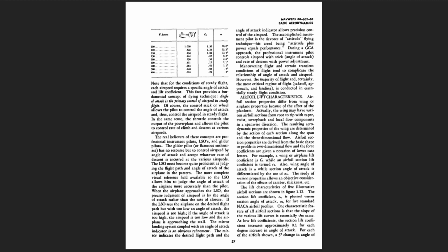The mirror landing system coupled with an angle of attack indicator is an obvious refinement. The mirror indicates the desired flight path, and the angle of attack indicator allows precision control of the airspeed. The accomplished instrument pilot is the devotee of attitude flying technique, his creed being attitude plus power equals performance.